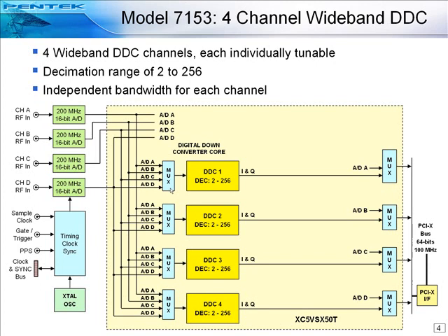Each DDC also has programmable gain and phase shift controls accessible to the processor across the PCI-X interface. In this system, we will be assigning one A/D converter to each of the DDC channels.